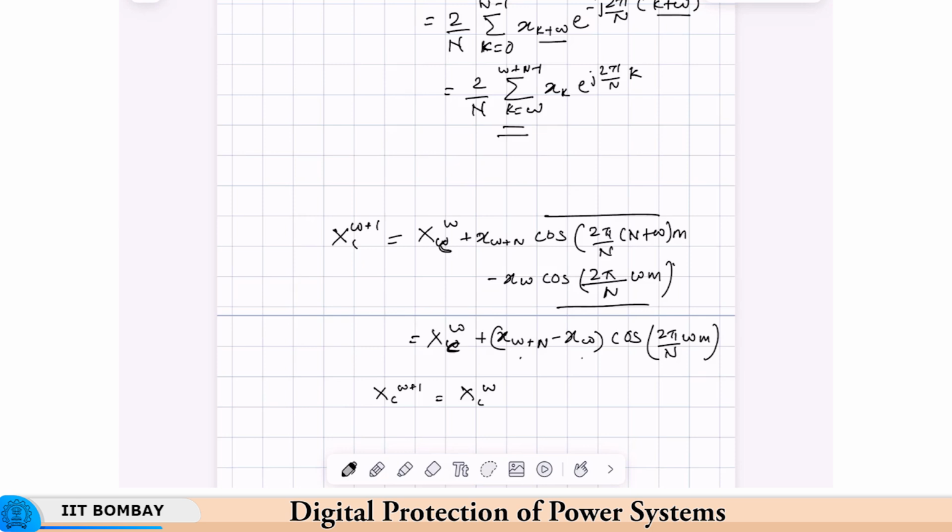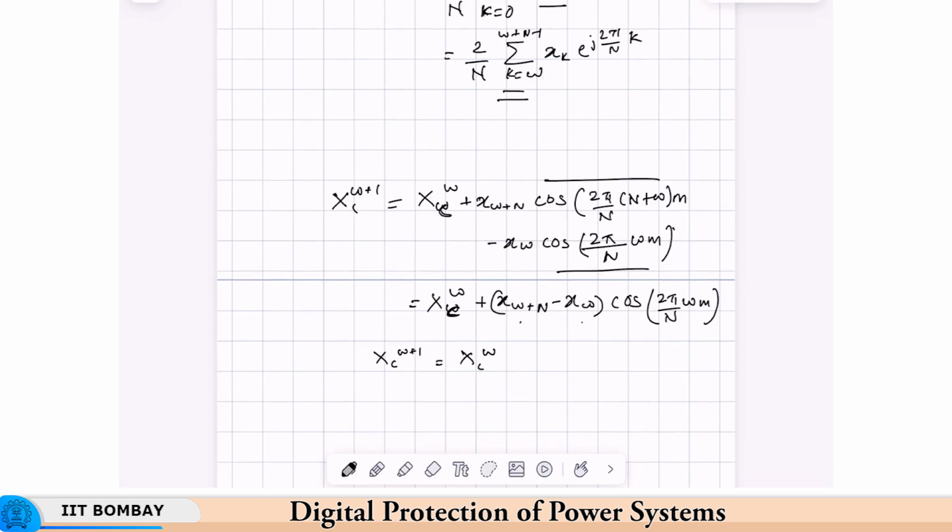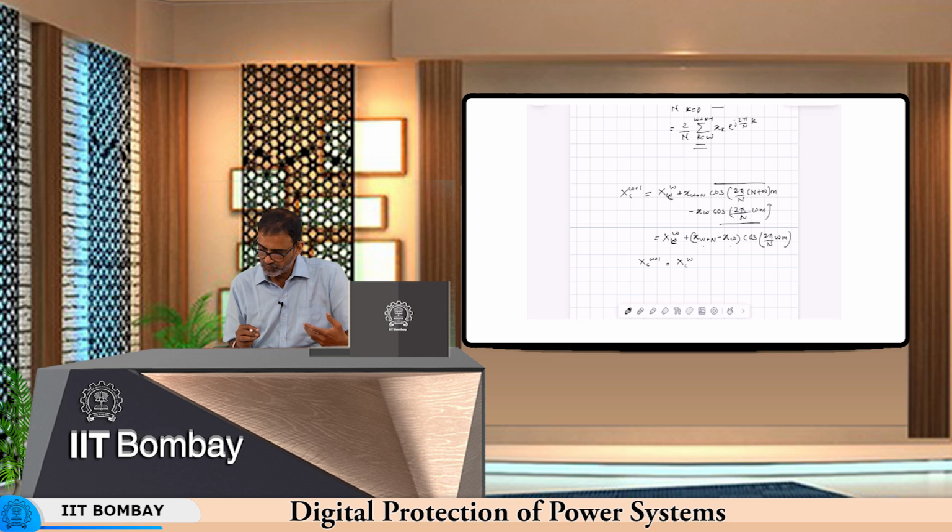But the phasor is always changing, because loads are being changed, generators are coming in, coming out, there may be a fault. So, that is why this computation has now been simplified to just one add and one multiply computation. I mean 2 add 2 multiply in a sense, but just an update. So, the recursive form of the DFT is just an update. So, it becomes a very efficient way of computing DFT. We have now succeeded in making it into an update operation.